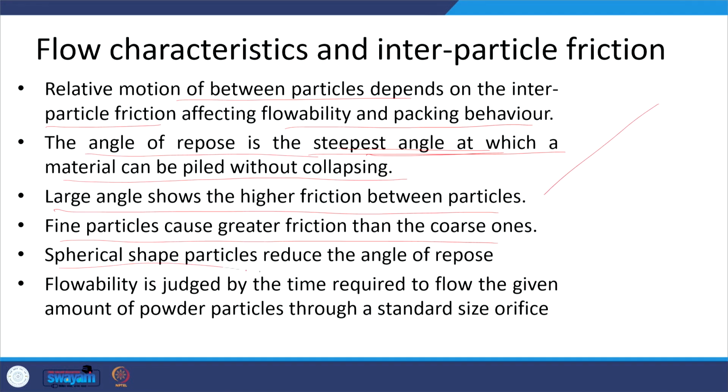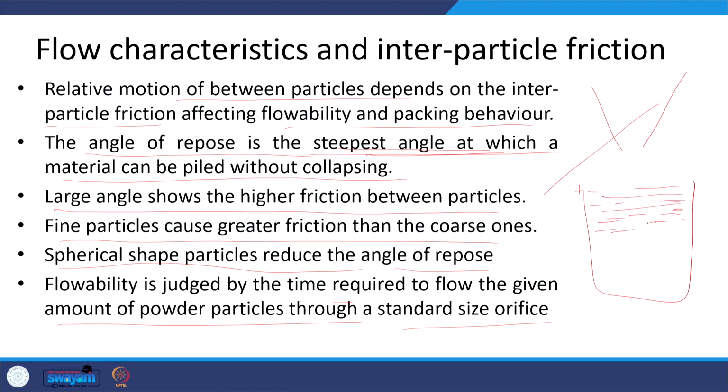Okay, spherical particles will reduce the angle of repose because of the reduced interparticle friction, and the flowability is judged from the time required to fill the cavity. Okay, the time required to fill a given amount of the powder particles into the mold cavity using a standard orifice size. So, say our orifice size is fixed, and this is the cavity which is to be filled in by the powder particles. So, how much time it takes to fill the mold cavity of a given volume using the standard size orifice, that time is used as a measure of the flowability.